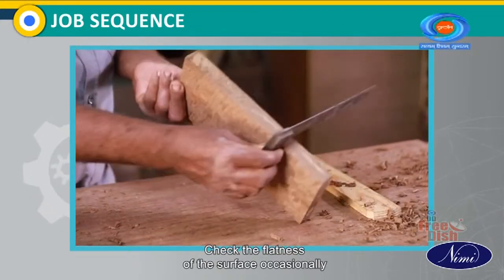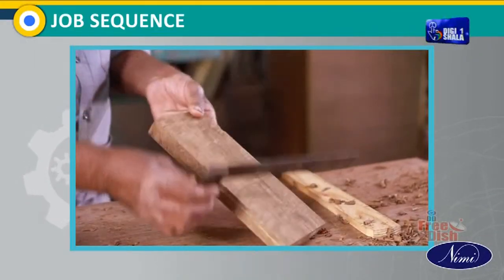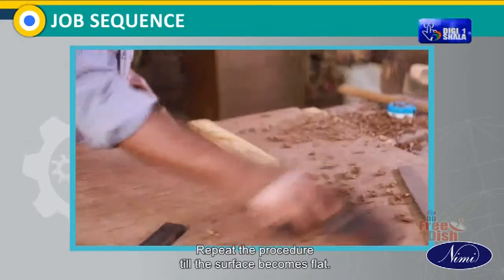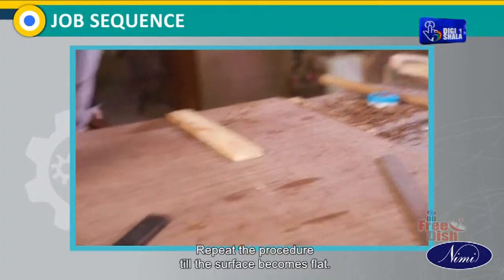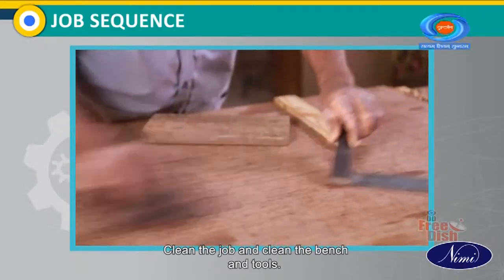Check the flatness of the surface occasionally with a tri-square or straight edge. Repeat the procedure till the surface becomes flat. Clean the job and clean the bench and tools.